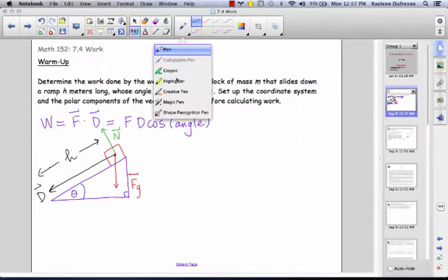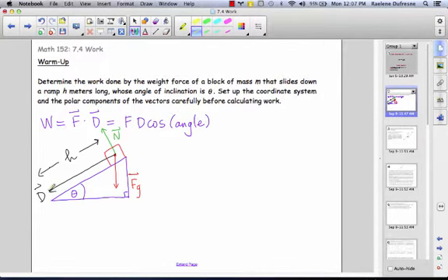So what we can see is a coordinate system here. We can take the origin to be the center of the block, and we can take the direction of the ramp to be the x-axis, and perpendicular to the x-axis is the y-axis. So we can redraw this in what we call a free body diagram. A free body diagram means that we don't have the real life diagrams of the block or the ramp. And so I'm still going to keep my x and y axes rotated for now and just redraw the vectors.